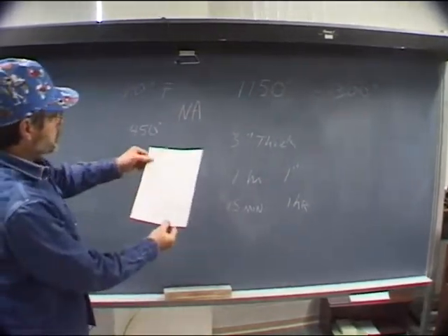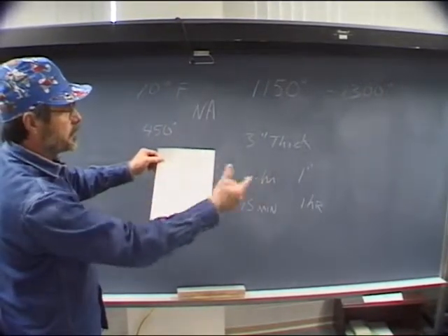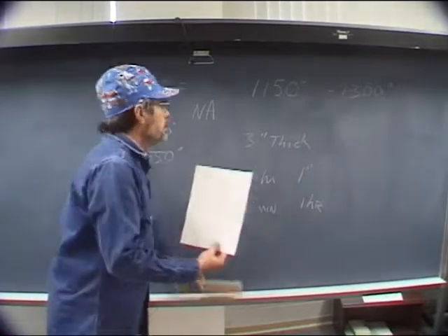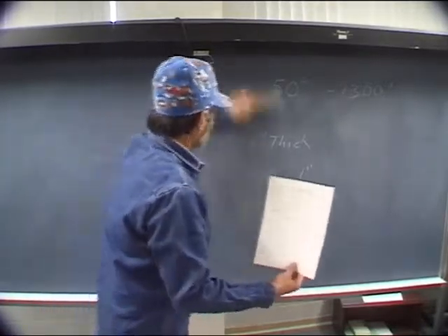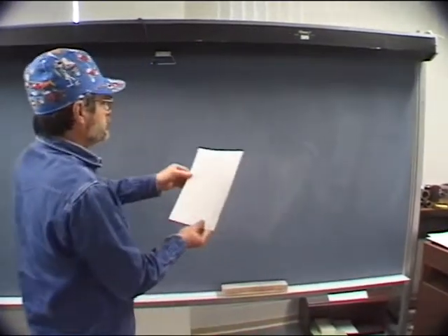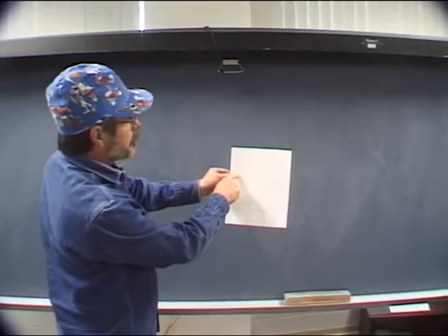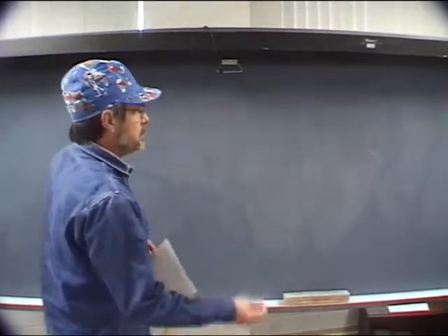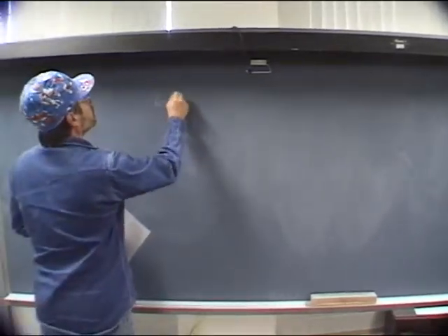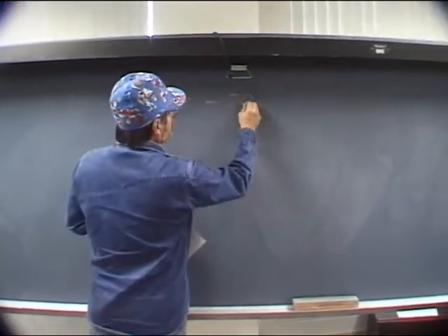Then the electrical characteristics. You're going to fill this information in, and all we're doing now is moving stuff straight over from our PQR to this form. The only difference is now we're going to give them a range. You'll notice here it says amps, and it's asking us for a range. A typical range: if you remember, we did our 6010, and what we actually recorded was 78 amps.